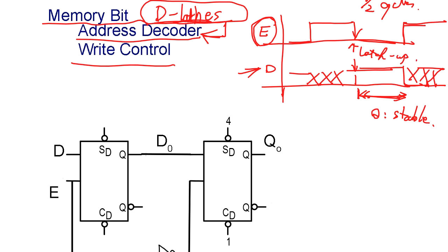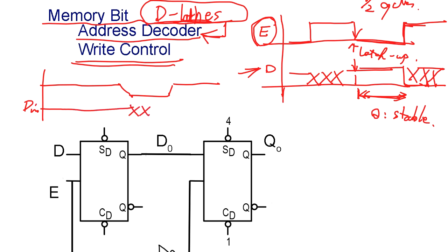Okay, so timing wise, there is a latch up point. Once it's latch up, half cycle, it holds that data, then goes away. So the write control for memory, when you write, you give a write pulse, and whenever data in, you write that data into the memory. I'm gonna change it around, and it better be stable before the latch up point. Then data is written into the memory. So memory needs the write enable.